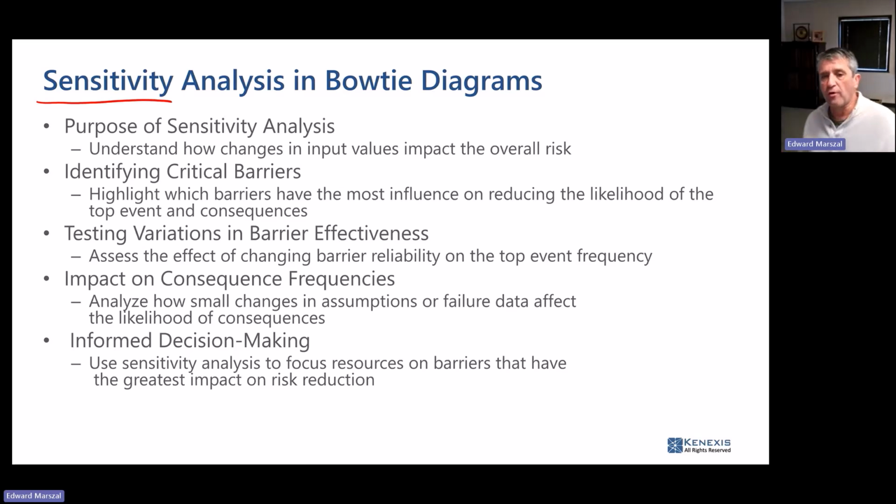So when you're performing this quantitative bow tie study, you have the ability to take barriers out or change the effectiveness of barriers and see how the risk profile changes and whether or not risk is tolerable. So if you put a safeguard into bypass, that converts its probability of failure to 1. How does that impact the full range of outcomes that are possible?